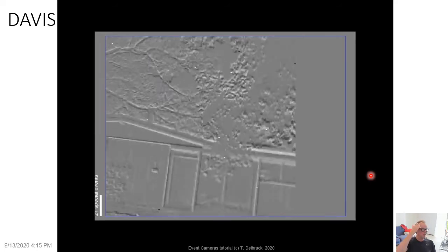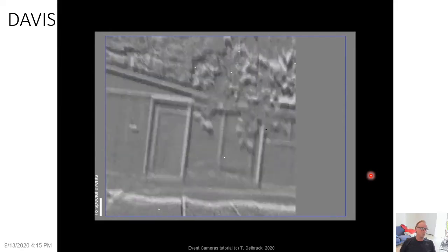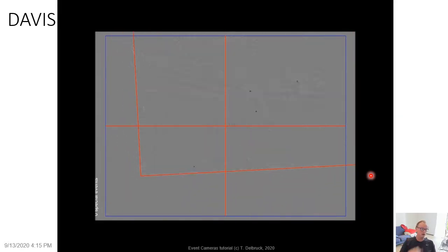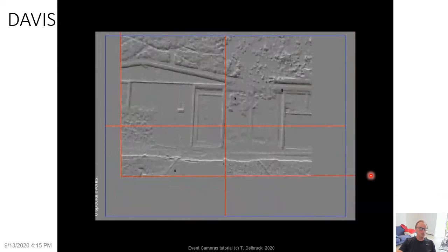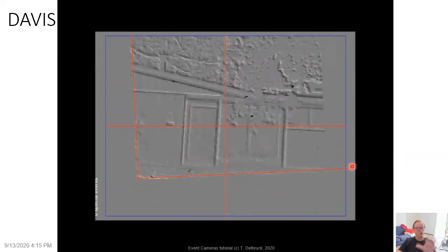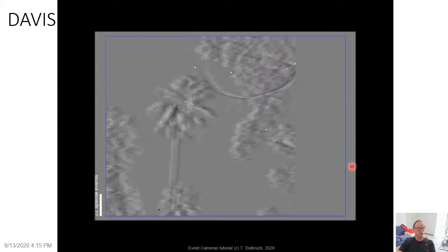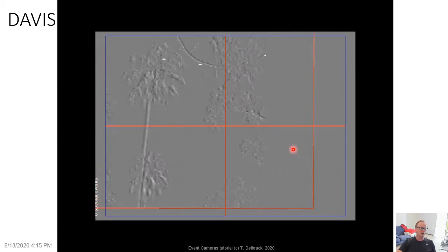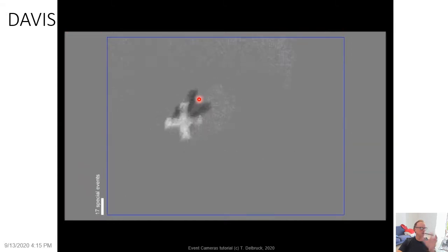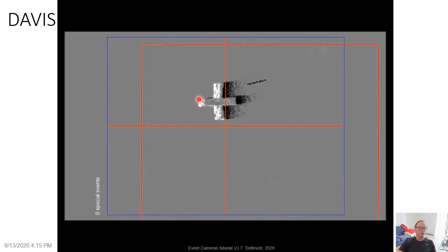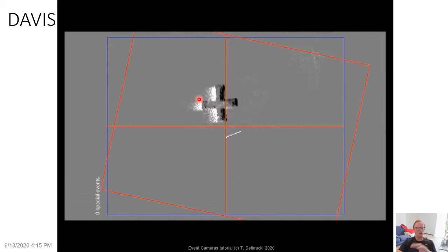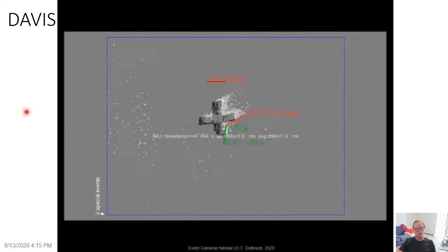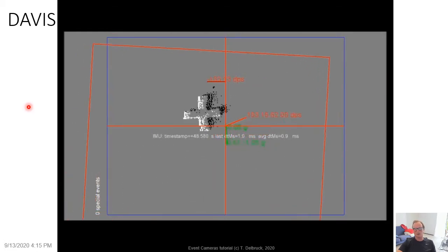And nowadays these cameras include an inertial measurement unit. We were the first ones to put this IMU on there. But this IMU now allows you to do event by event derotation of the camera, steady cam. And it shows here how even a rapidly vibrating camera can be stabilized by using the information from the inertial measurement unit to remove the motion of the camera, or actually just the camera rotation. So I hope this is helpful to explain something about the nature of this DVS output. But I'll go on now.